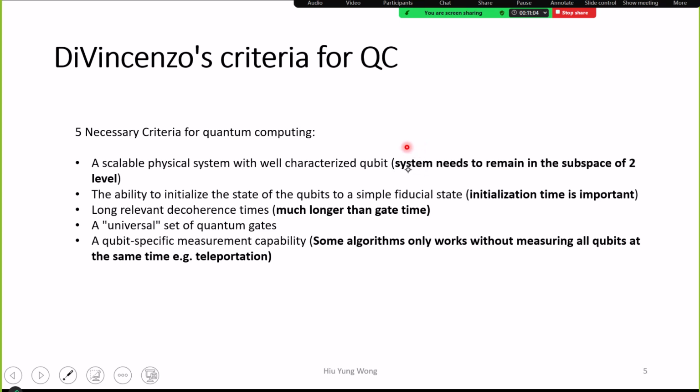Transmon, yes. We use a Josephson junction and a capacitance to form something like an LC tank. Then we have many levels, equally spaced, but because we use a Josephson junction, it is non-linear. As a result, we have anharmonicity. Remember?